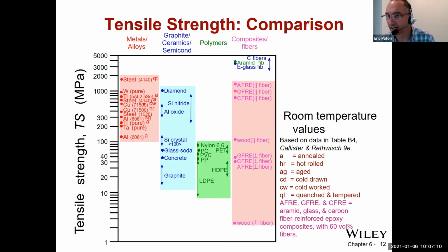What's happening is we're giving time for very small precipitates, tiny ceramic particulates, to naturally form in the material. So it's becoming a bit of a composite, I guess you could say, to give it some extra strength on a nanoscale. These are very small ceramic particles, and these inhibit the movement of dislocations within the material.